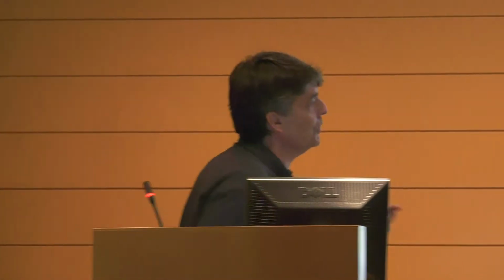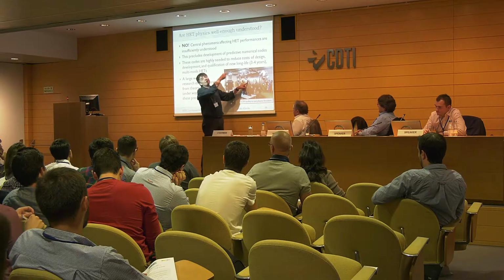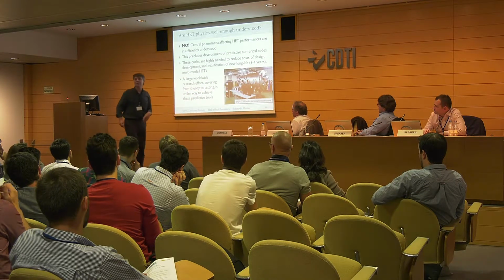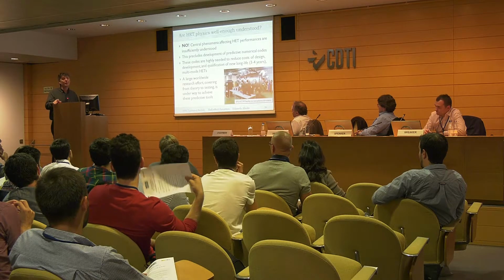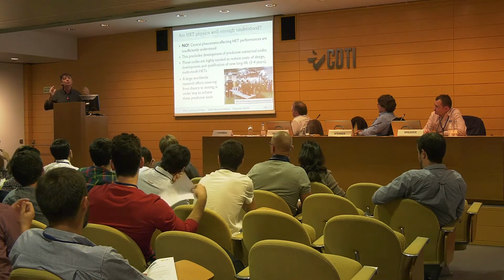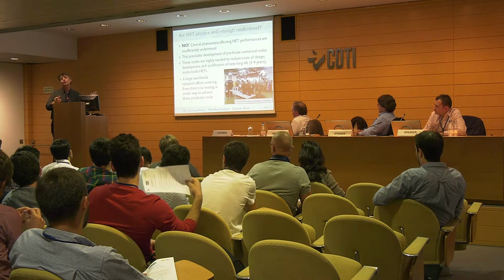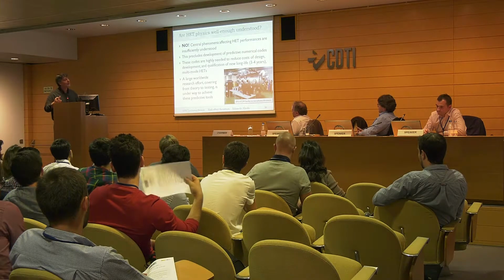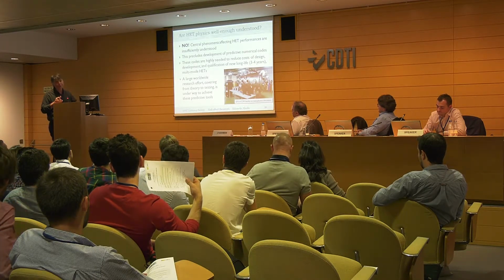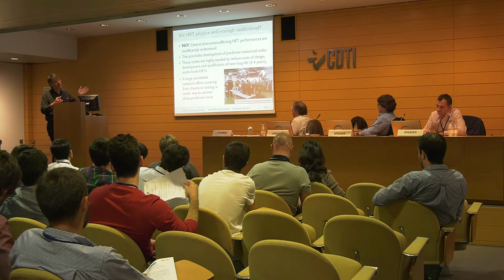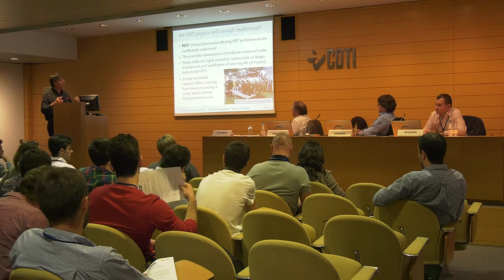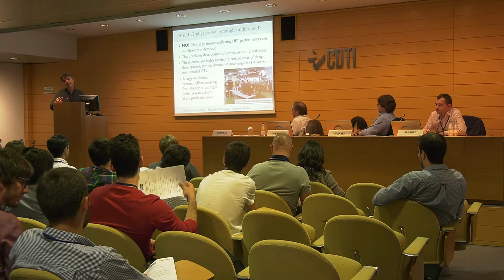If we don't have full models, we need to put the thruster in a vacuum chamber like this for 4 times 2 years, perhaps for 8 years, because from time to time we need to open it to see what happens. We have problems with the operation of the vacuum chamber. So this is a big problem now that electric propulsion is so important and wants to go so fast. The issue of qualification is an important problem, and we need to have better models and then better simulation. Because we need to solve these problems that have been there for 50 years, okay? And there is a large worldwide effort, both in theory and testing, to try to get these predictive tools, okay?